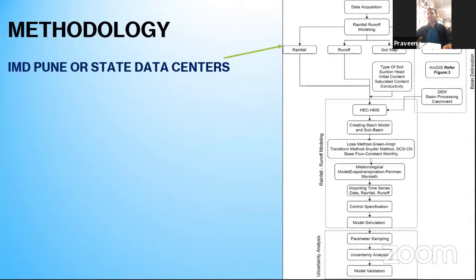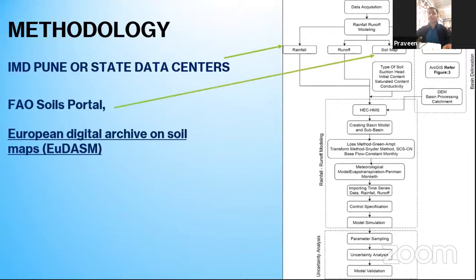Apart from that, there is runoff data. Runoff data is very important because rainfall data is easily available nowadays. You can access it from RCM and GCM models, and IMD has given free data to everyone. So rainfall data is not an issue nowadays. The problem is the discharge data, and mostly nowadays discharge data is also available from the WRIS website of India. The thing is, in my experience there is also a lot of missing data.